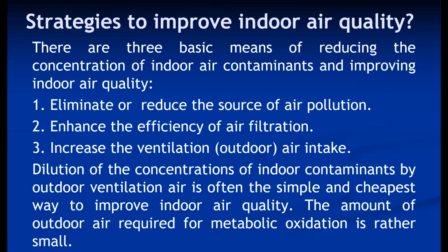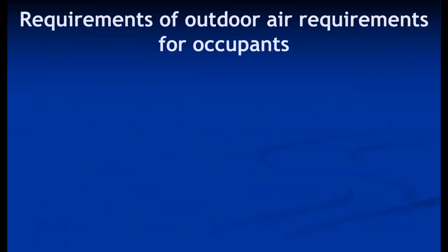That's why in most hospitals, this solution is used, so the maximum amount of fresh air is utilized. If you see the distribution of fresh air, almost 40% fresh air is utilized there, and in some hospital operation theaters, almost 100% fresh air can be used. So these are the strategies to improve indoor air quality: either reduce the source, improve the efficiency of filtration, or increase the ventilation. These are the 3 strategies you can have.